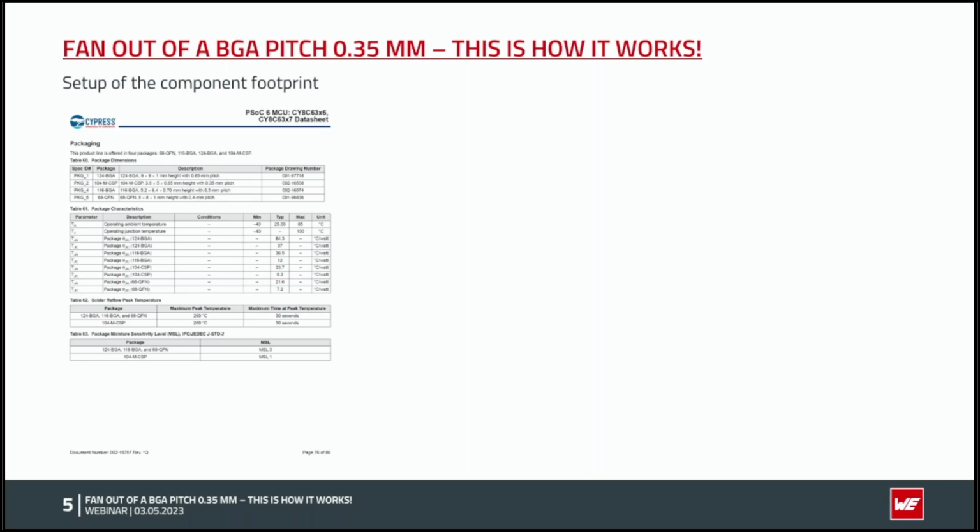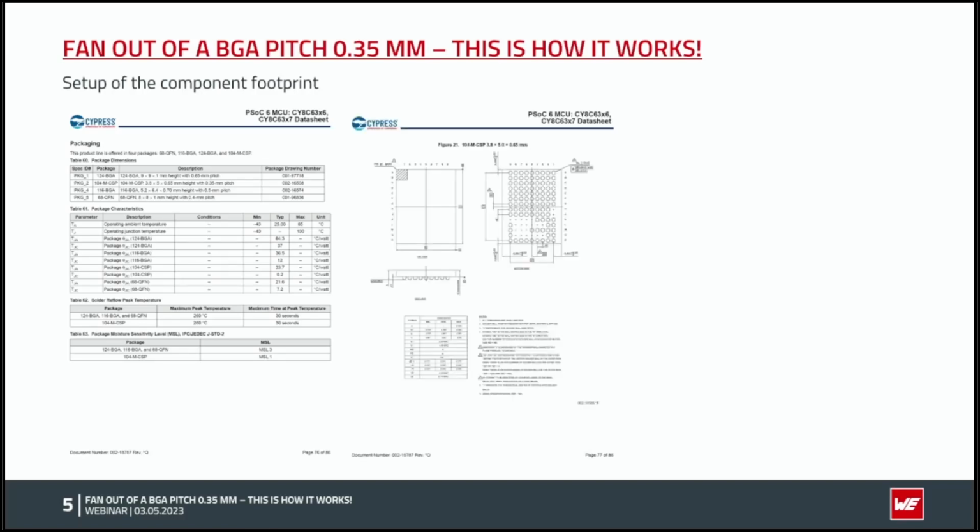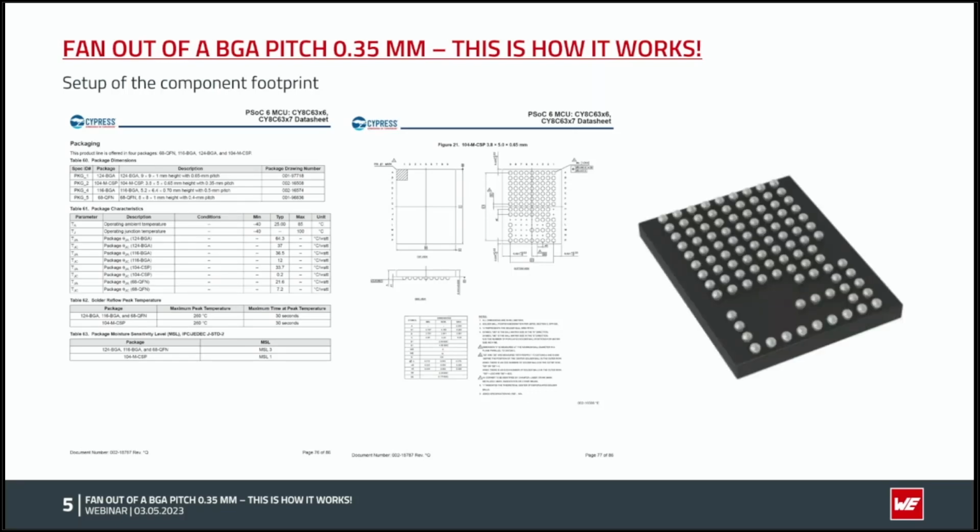After setting up the schematic for the part, you need to set up the footprint. There are different libraries available online where you can download information, but please take care, because there are often mistakes in those free libraries, so you need to check them if you are going to import them into your local database. Beside the parameters like MTBF and thermal parameters, you also have the mechanical parameters, for example the footprint or the dimension of the part itself.